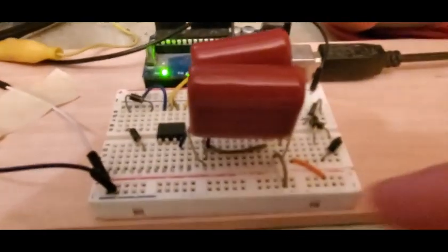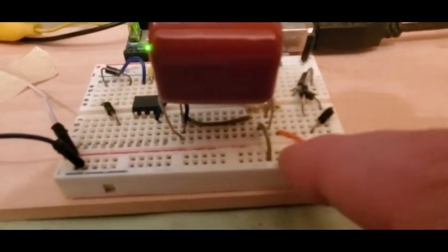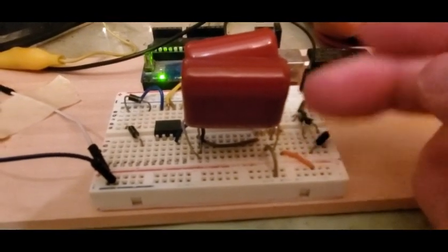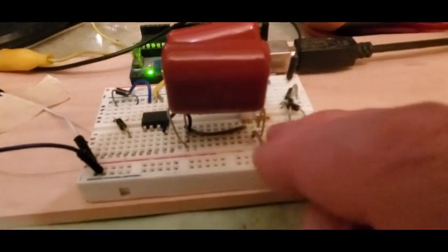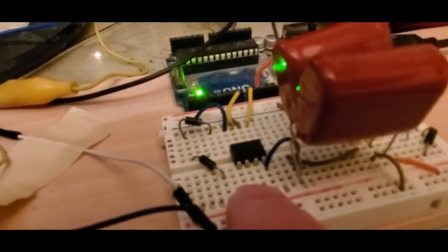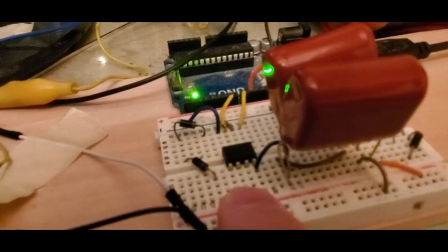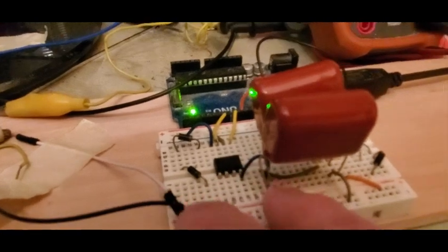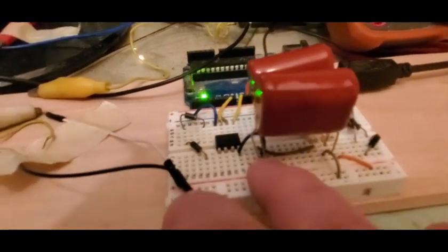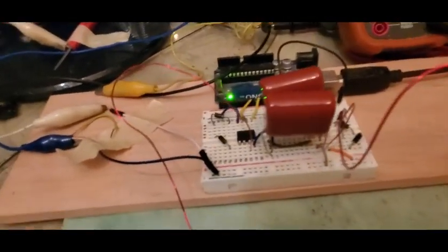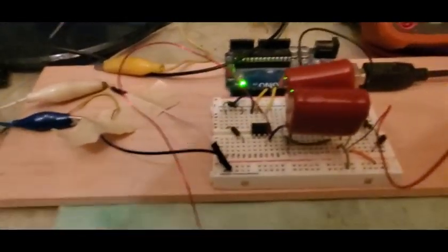I said we wanted 20 uF, so 2 of these caps, and so they get charged up, and then it shuts off. And these are solid state relays, so it's all opto-isolated. Now if we put a coil between this leg and then out to that part of the switch there, when that switch turns on, the cap discharges around to there. And that's your LC tank circuit. So we'll do this the old-fashioned way first, and then I'll show you the glory of the oscilloscope.